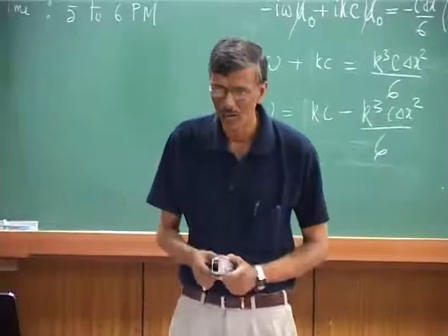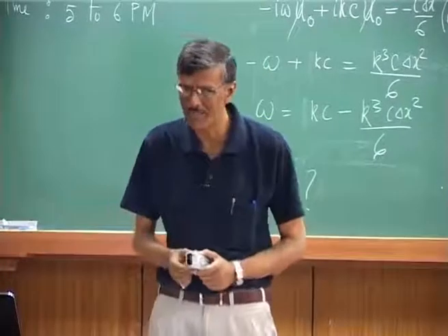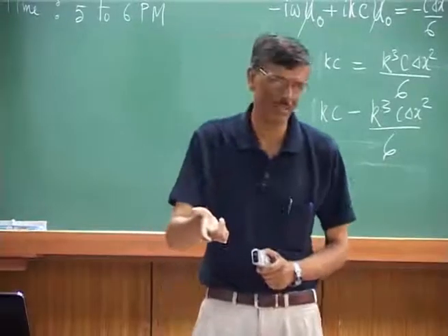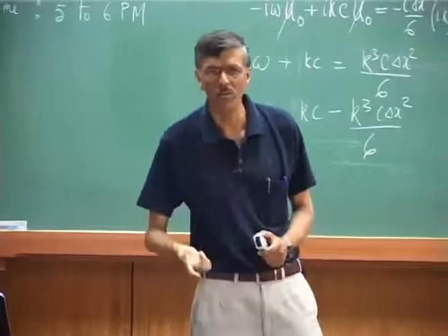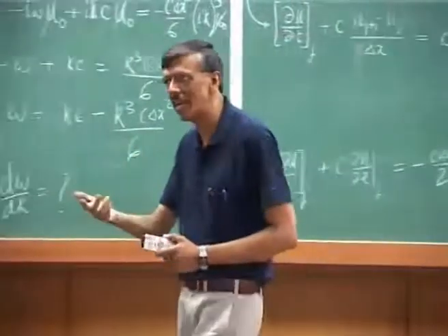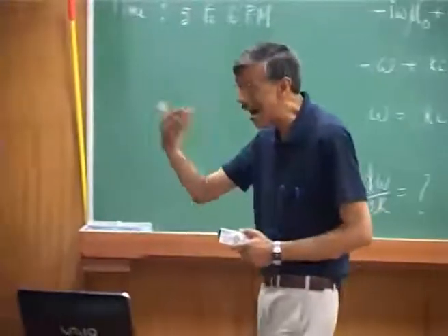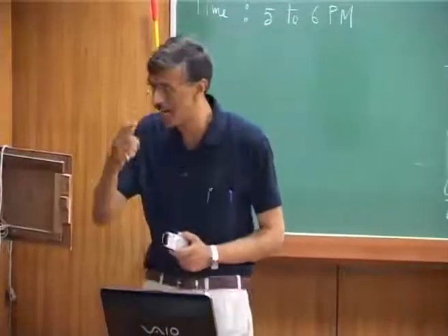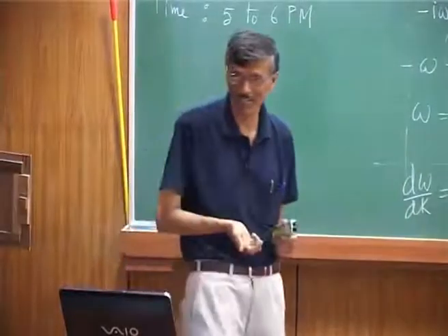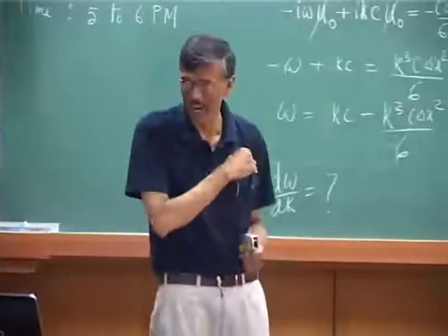The answer is no, because you are then going to alter the physics of the problem, since physically there is already a second derivative term. So, what you may like to do is numerically stabilize those cases by adding higher derivative terms. I would not add a second derivative term, but I would add, let us say, a fourth derivative or sixth derivative, and that is what we have been trying to do.